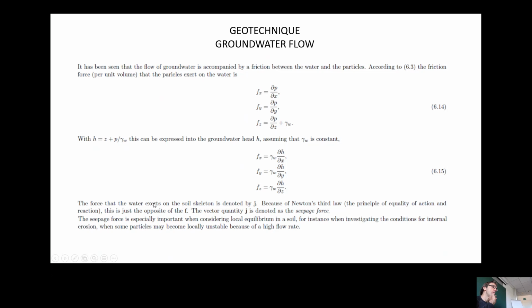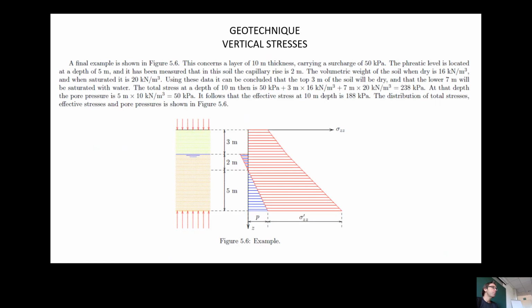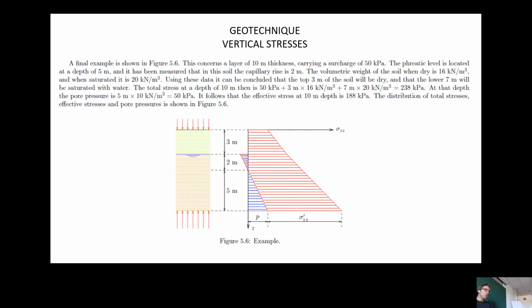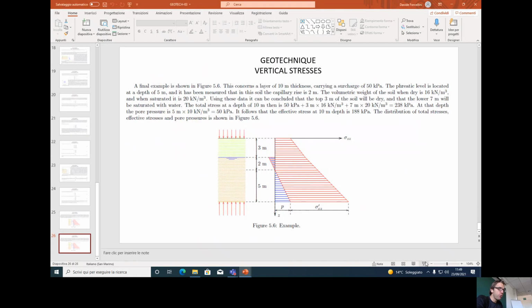The seepage force is especially important when considering local equilibrium in a soil, for instance, when investigating the condition of internal erosion, when some particle may become locally unstable because of a high flow rate. In the final slide, I will eliminate these two sentences because they are not really important for us. So let's see at this point the last example for today